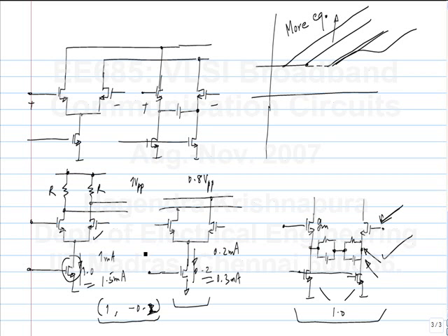Yeah, I mean, essentially in this case, you have to define the location of the 0, right? That is the coefficient, so to speak. That's the only degree of freedom you have. In this case also, the second coefficient is the only degree of freedom. I mean, you can increase both, but that's not the relevant thing. For equalization, the ratio of this to the main one is relevant. So similarly, in this case, the location of the 0 is the relevant quantity, and that you change by changing the value of R and C. Perhaps you can switch different values of R or different values of C if necessary.